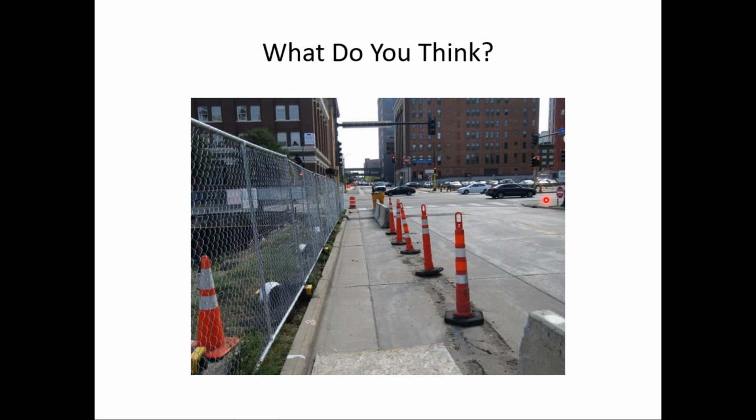And then the trucks left, and the trucks are probably going to be back the next morning. So rather than go to the effort and expense of putting the temporary traffic barriers back, they put in these channelizers, tubular markers, I guess you call them. But now, is that a detectable detour route, alternate route? I would say no, these are not a detectable edge. And so this is no longer a detectable route, at least on our right side here.